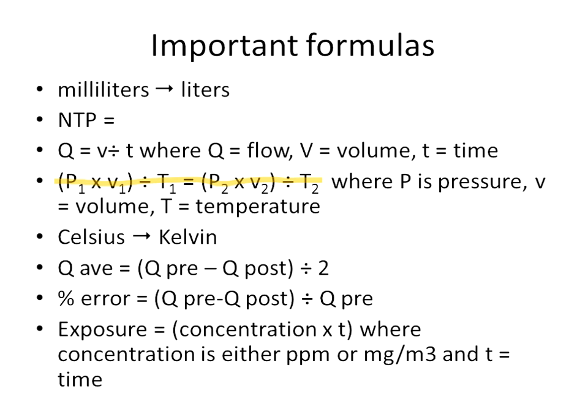Percent error: you've set your pre-cal, you've done your sampling, you've gone out in the field, you've come back, or really your post-cal as soon as you take the medium off of the workers before you bring your pumps back to the lab. Now you're doing your post-cal. And you want to make sure that these values are within 10% of each other because, and you should know the answer to the rest of that statement.